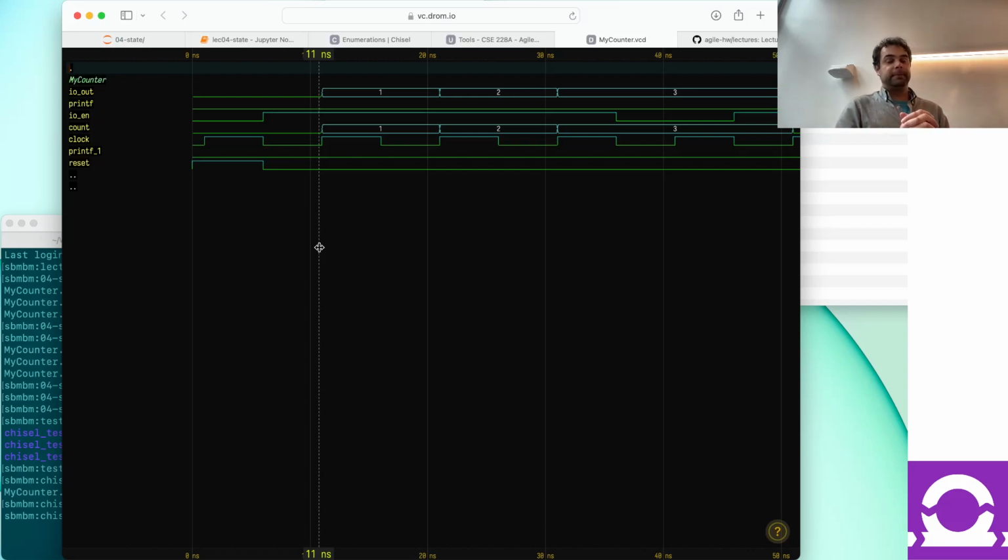Really, really recommended. One of the things I did, I guess two offerings ago, is I turned on waveforms by default for the homework assignments. Waveform usage jumps dramatically. So as soon as you turn on waveforms, I put it on by default. Go dig around in the test run directories, you'll find it. If you find it confusing to keep having to figure out which is the most recent test run directory, there's a way to hard code the output directory, and if you run multiple times, it overwrites it, which sometimes makes reading waveforms easier.